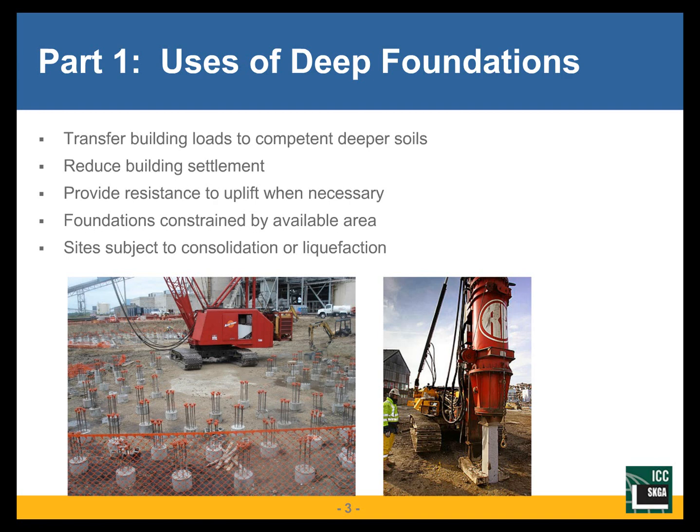And in cases where we really don't have very much bearing area at the surface, we may use deep foundations simply because we're constrained with the amount of area we have. Where we have sites that are subject to consolidation, that is very young clay or mud sites, or where we have seismically induced liquefaction, then deep foundations can also be used to help us there.